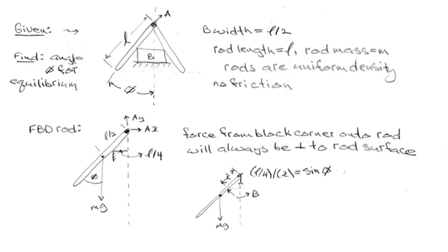Now I can start summing the moments around that pin. I know how to apply B, which is the normal force coming from the box, and I already know the weight. If I sum the moments around pin A, I can get B in terms of the weight, because of the geometry of the normal incidence plus the location of that corner with phi, which I have expressed here as x. This came out of the geometry of the problem.